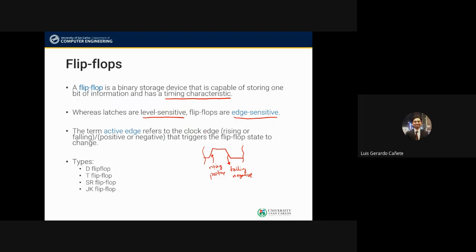Yeah, so if we were to use flip-flops, then even if the clock had, let's say, some skew problems, so that it would instead look something like this, as long as the skew is symmetrical, then the timing for when we transition is always fixed.